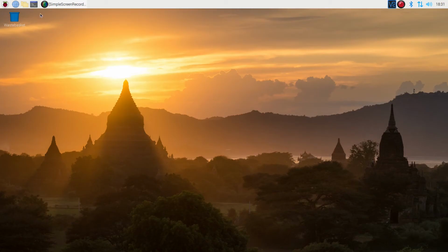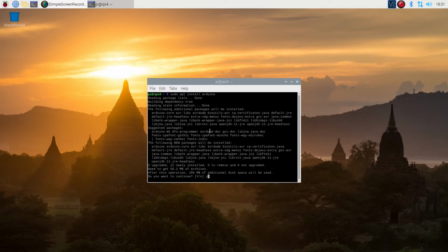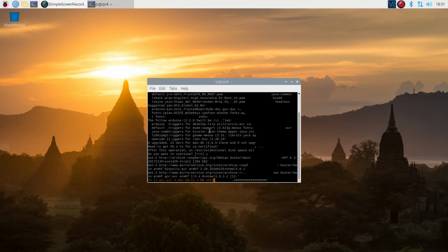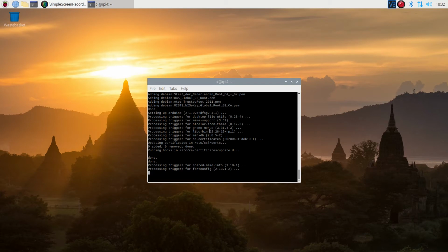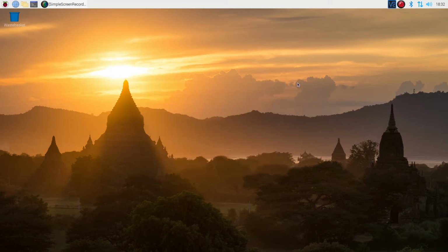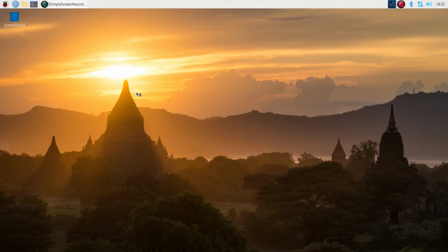If you have one of the more powerful Raspberry Pis, then you can install the Arduino IDE directly using sudo apt install arduino. Otherwise, you can install an appropriate IDE from the Arduino website, perhaps for a Windows laptop, etc. You only need the IDE for the program code for the Arduino. Once you've uploaded the code, then you can switch to any Raspberry Pi instead. Once installed, you'll find the Arduino IDE on the programming menu.